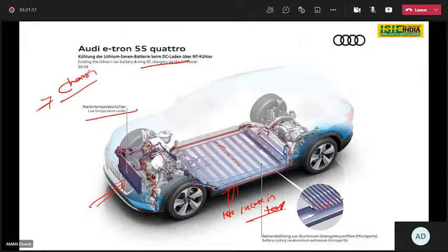operation? So this coolant, as soon as it hits a certain temperature, let's say 40 degrees Celsius, this cooling process comes into the picture. It will automatically start by itself, and with this particular flow passage, the coolant flows in this direction through all the passages and takes all the heat. It is maintaining the temperature, reducing it to near about 25 degrees Celsius, so that it stays within the working temperature range.